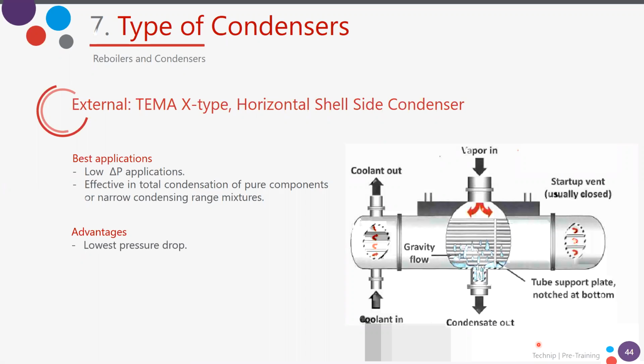But if you are using HYSYS, for example, the part of HYSYS that designs heat exchangers is EDR, and with this program you can see the velocity on the shell side and also the pressure drop.